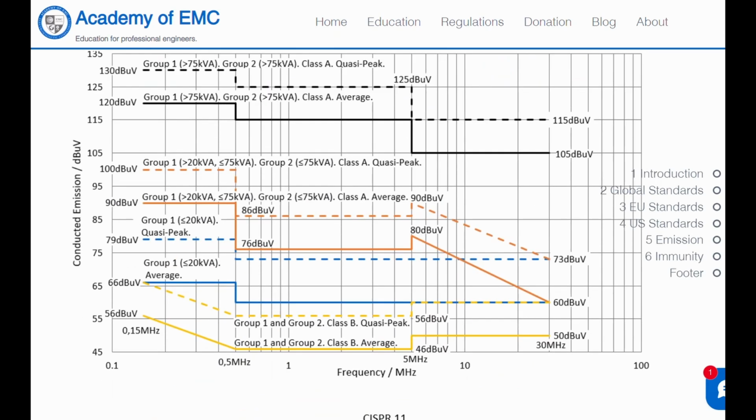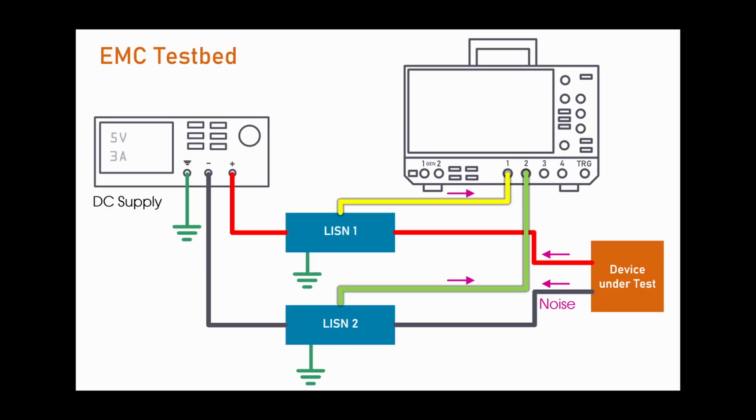I think if the MXO could be used, then the benefit is that more frequent EMC testing could be done during development. For conducted emissions testing, I wanted to use the maths capabilities to separate out the common mode and the differential mode noise.